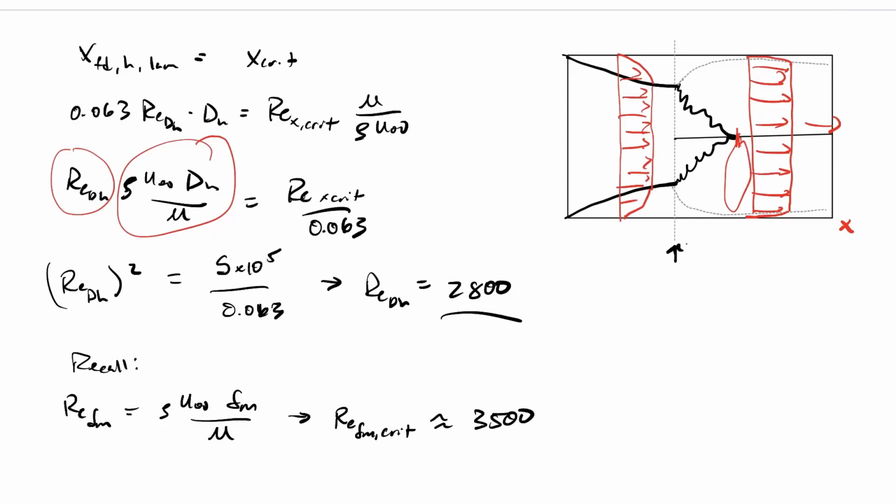The turbulent eddy region is trying to grow because of constant chaos and movement. They come to some kind of truce. The forces end up balancing for the growth of the viscous sublayer versus the growth of the turbulent region. So at the point of being fully developed, this viscous sublayer will stop growing. Okay. So that's what the velocity profile looks like.